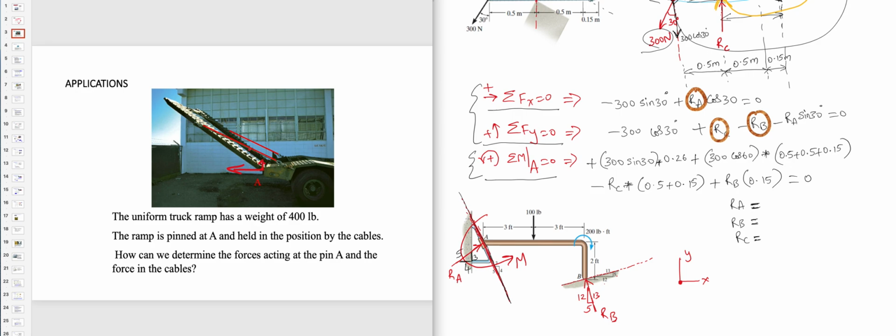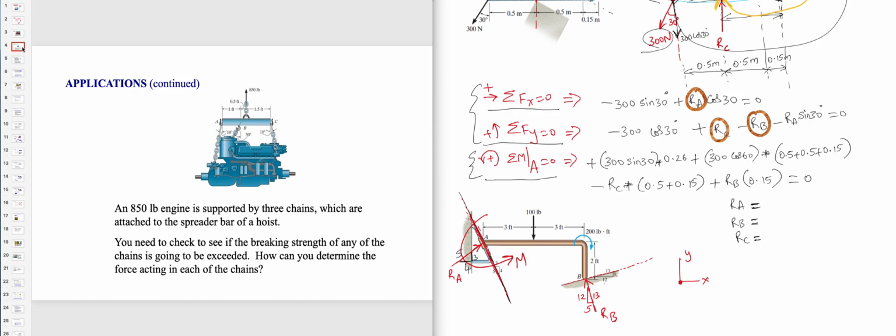And we have to replace the ropes with tensions. This is one tension, this is the other tension. If they're both symmetric, if they're both parallel to one another, we can treat there are 2 ropes, so we write this as 2T if we are doing a 2D problem. And we have the weight of the ramp, W, acting vertically down. So, for instance, in this case,